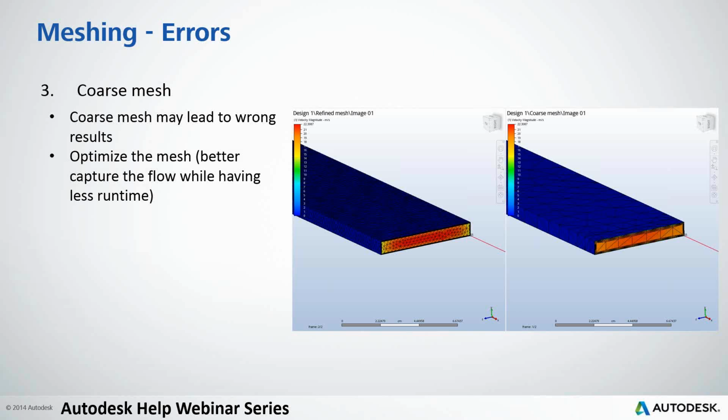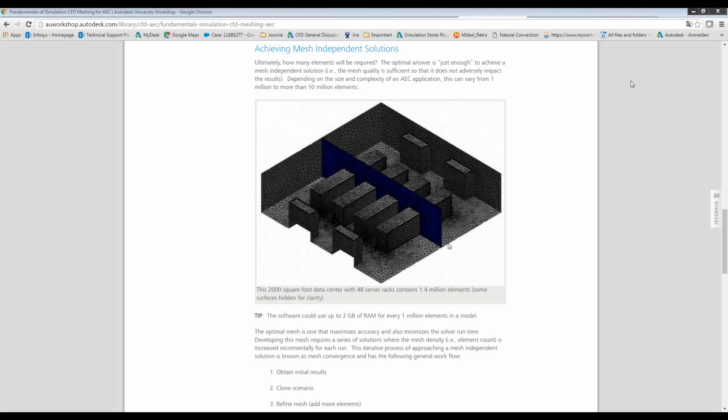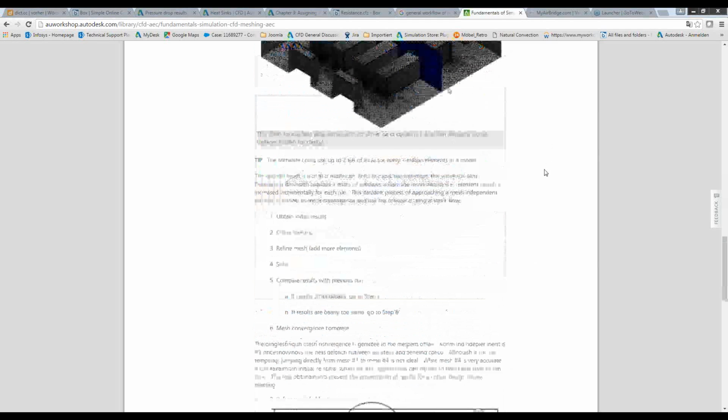While you're grabbing that and sharing, we did get a question about how you would do the conductivity normally when you've got a resistance and you're trying to do heat transfer. Typically, what I'll do for a starter is a weighted average of how much is fluid and how much is solid, kind of the reverse of a free area ratio, and then do the weighted conductivity between the fluid and the solid. But you're probably going to end up having to weight a little bit higher of a conductivity.